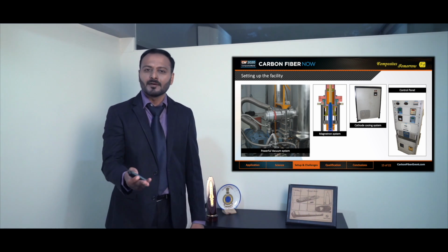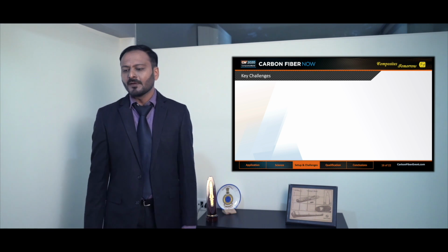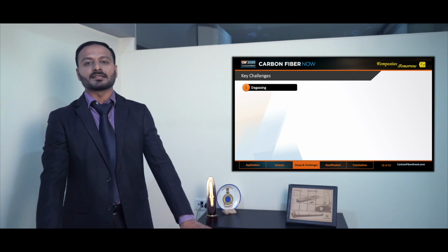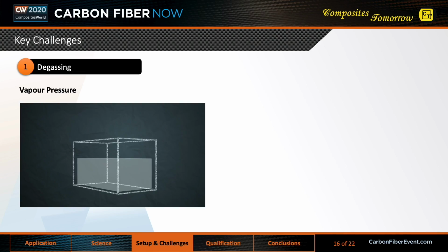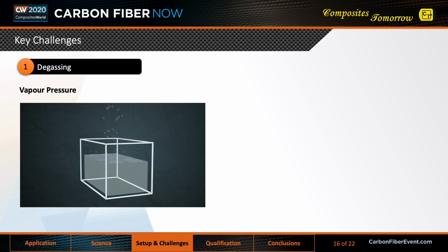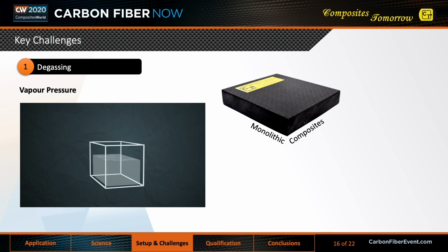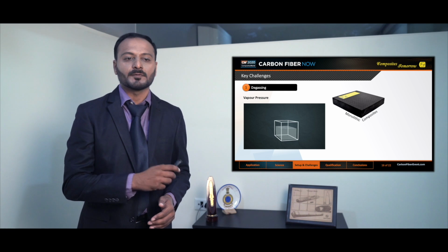Yes, there may be a few challenges that we may need to overcome during the process. The very first that I envisage is degassing. What is degassing? Well, we all know about vapor pressure, or maybe the video here shows it. But all our composites, even the monolithic composites, will have resins, and at 10 raised to minus 6 millibar, to maintain the vapor pressure, the resin will continuously try to emit gas, which will be collected as the gas of the system and impede our process of sputtering.